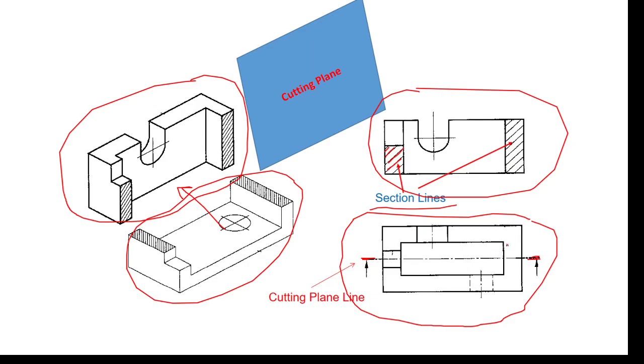Looking at such a view and seeing a cutting plane line, we can directly understand that a cutting plane has been used for outputting the corresponding sectional view. In the format we have arrowheads. Arrowheads are to be placed in ISO format, bringing the tip of the arrows into contact with the midpoint of the thick portions.